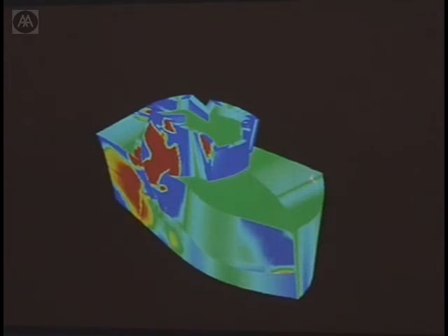In this case, we're looking at the amount of compound curvature existing across the surface, which is basically the reciprocal of the square root of the two radii of the biggest and smallest circle on a curve. That allows you to calculate how much it is curving. We knew in this case from material research that this is going to be clad in those famous little titanium panels that you know. A titanium panel has enough inherent flexibility.